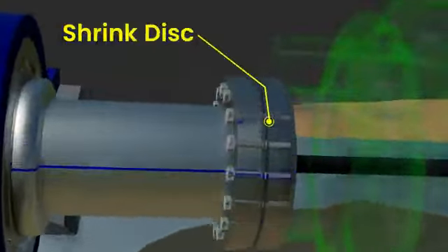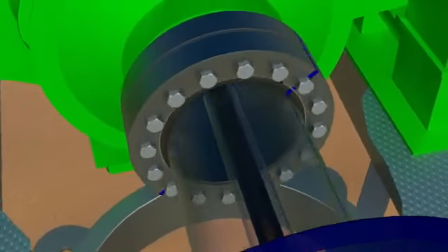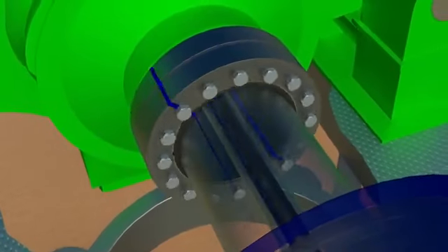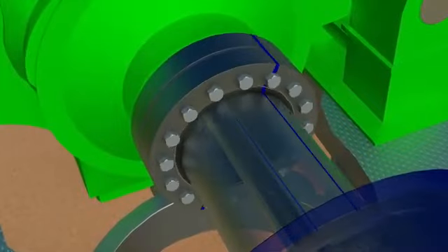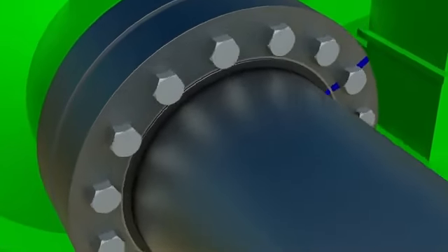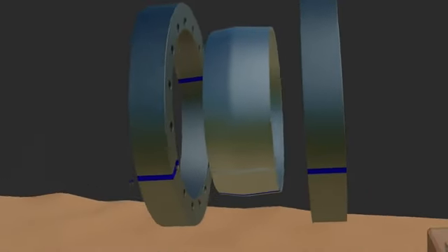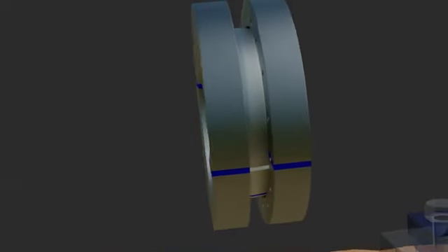A shrink disc coupling connects the main shaft to the gearbox input shaft. The gearbox has a hollow input shaft, and the main shaft is inserted into it. A shrink disc coupling functions as a high-strength, keyless mechanical connection used to lock a hollow shaft onto a solid shaft. A shrink disc fits on the outside of a hollow shaft hub. It squeezes the hollow hub so tightly that it grips the solid shaft inside it, effectively fusing them into a single unit during operation. A standard shrink disc consists of 3 main parts. First, a ring with a tapered outer surface called the inner ring. Second, two rings with tapered inner bores that match the angle of the inner ring, called the outer rings.